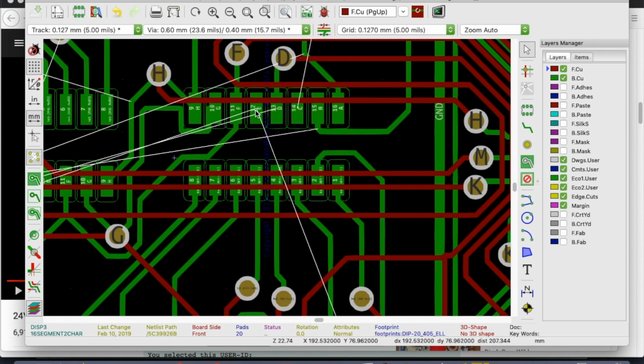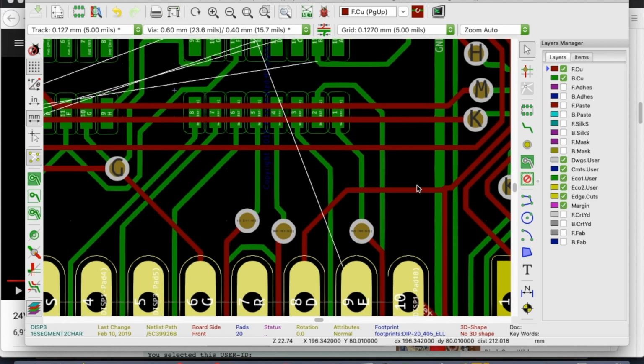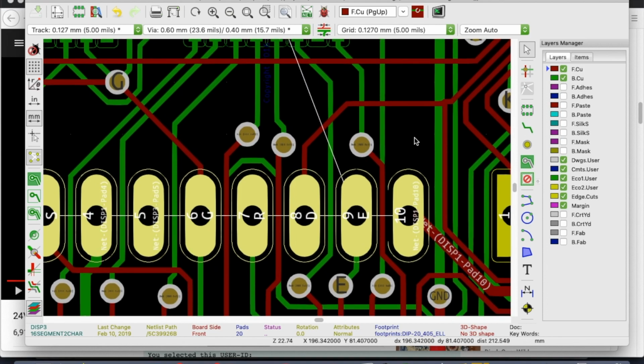Okay, so if we're running a green trace, which we have to since this is only on the green side of the board, we can go around here, we can cross over these. Now the trick is we have to get to here somehow. So if we nudge this wire over a little bit, maybe there's enough room to squeeze through here. We can go over that one, over that one, over that one, and we can go right onto this via here. Then we're good. So let's see if we can do that.